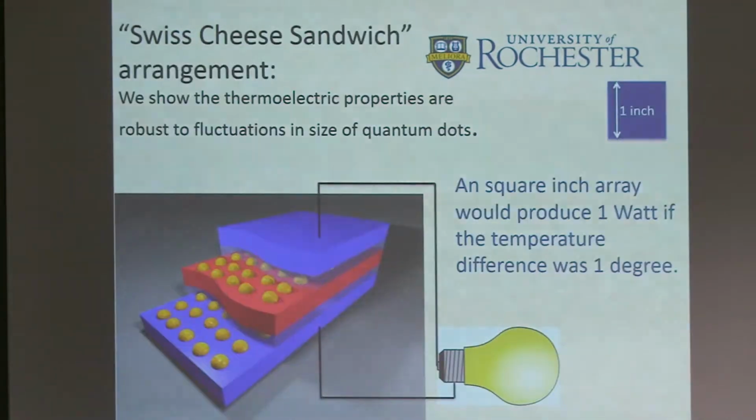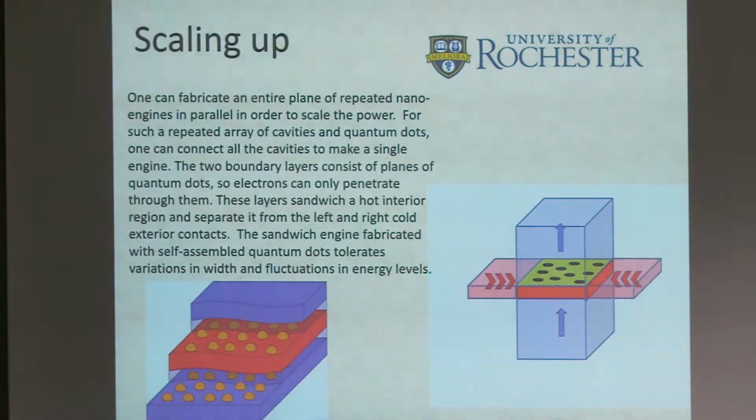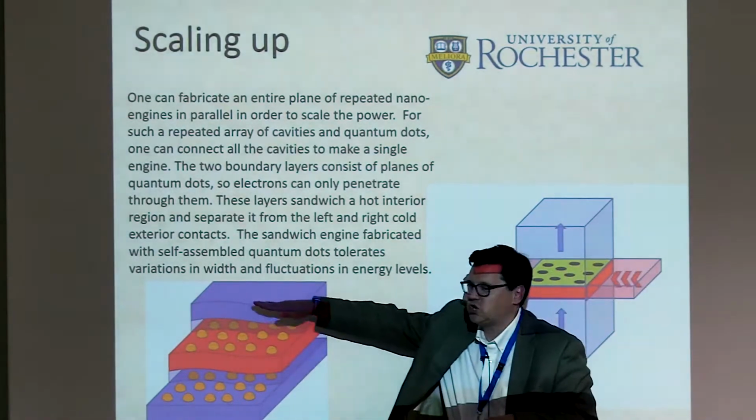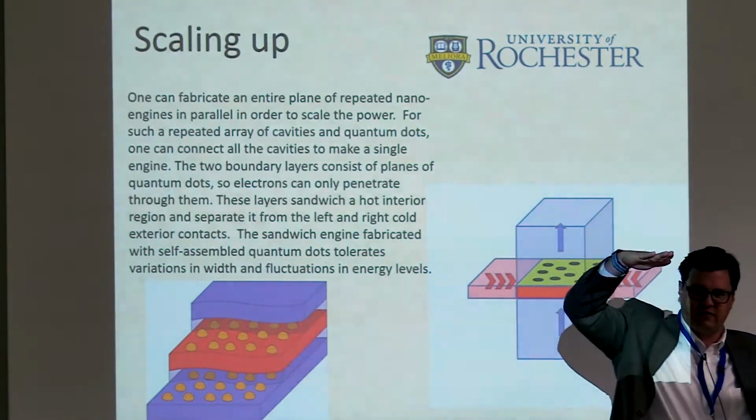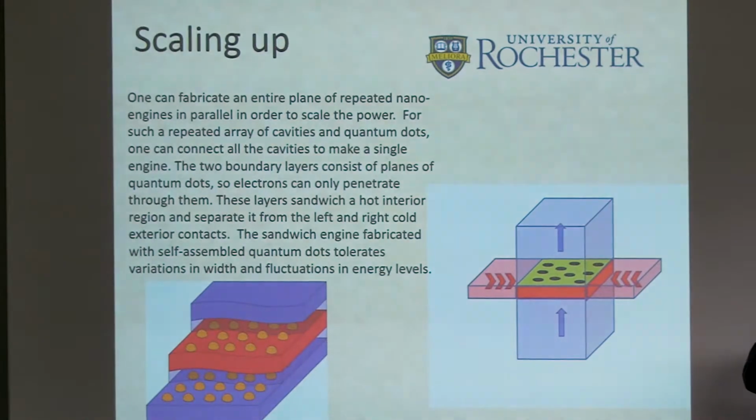How do you tune the levels? Yeah. So what you could do is a band gap kind of thing, or you could use an edge singularity. They call these a Schottky barrier. If you put a Schottky barrier here, that would tend to lift the energy levels on the right up, and down below. And of course, they won't be all exactly the same. There'll be some scatter, but we also studied this point, and we showed that even with some disorder in the position of the resonant levels, you still get good performance because the scatter is going to be smaller than the total energy difference on average.